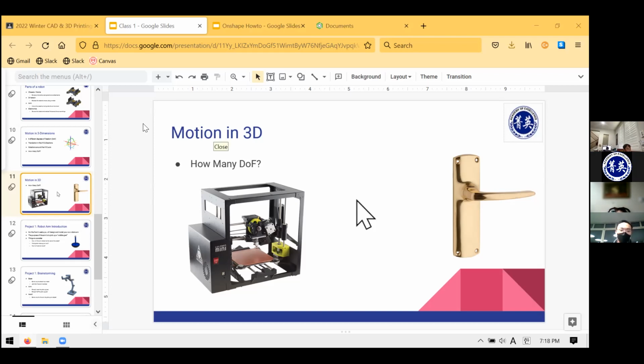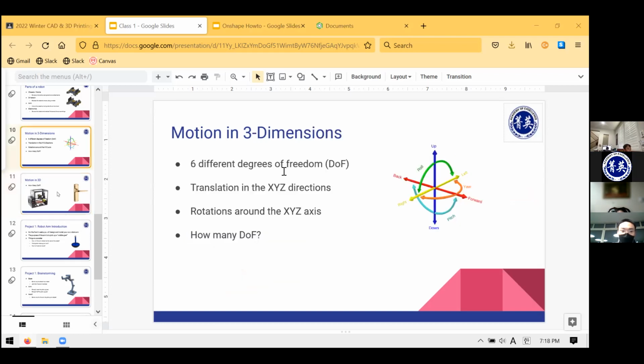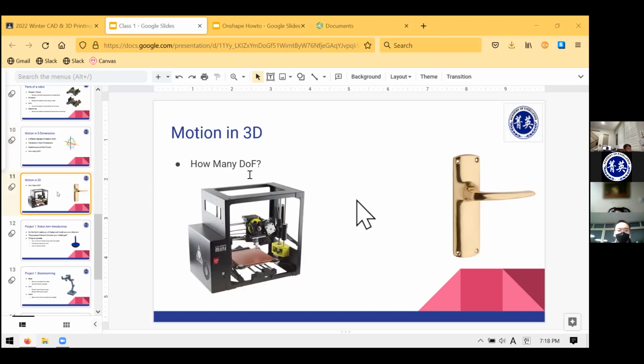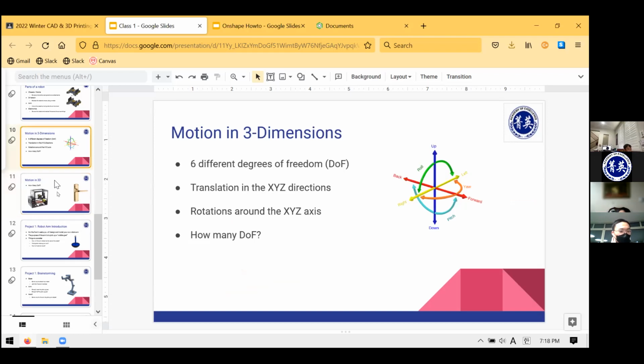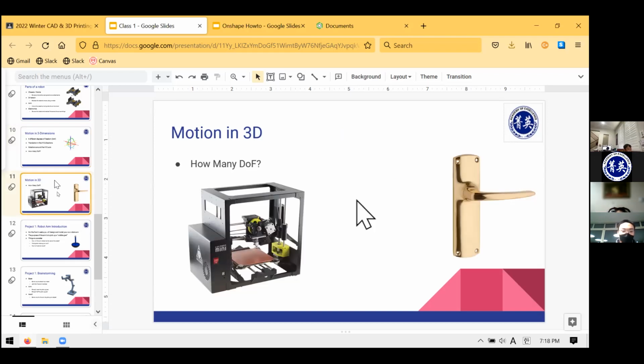All right, I see one response: the door handle is roll and pitch. And so I guess the way I introduced the question is a bit of a trick, because usually these terms roll, pitch, and yaw are defined on a specific coordinate system. So yeah, you're correct that the doorknob has basically 1 rotational degree of freedom. You could call that roll, we could call that pitch, and we could call that yaw even. It just depends on which way you look at the doorknob, if you're looking at it head on, or looking at it left and right. If you're looking at it head on, like you're walking towards the door, then conventionally, that's probably the roll.